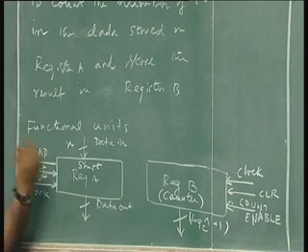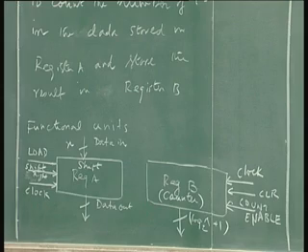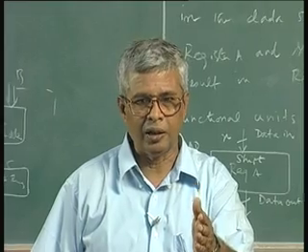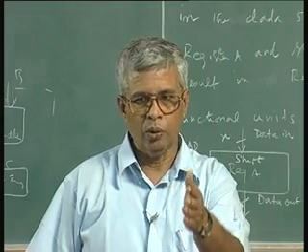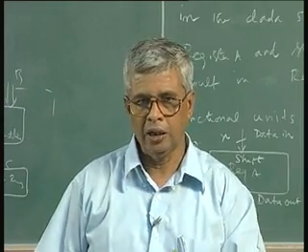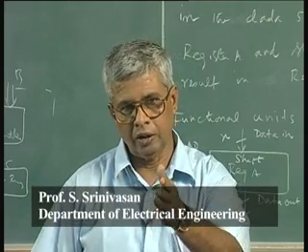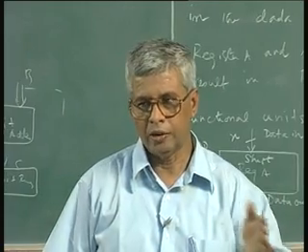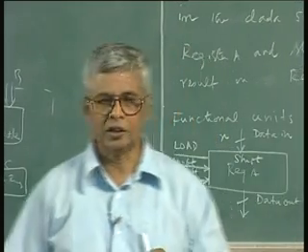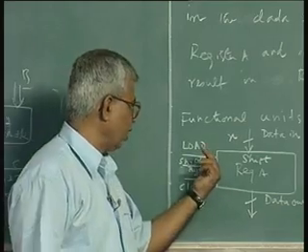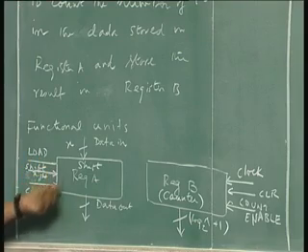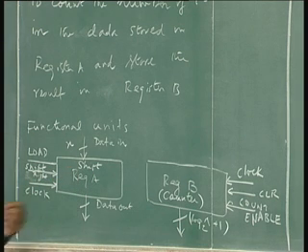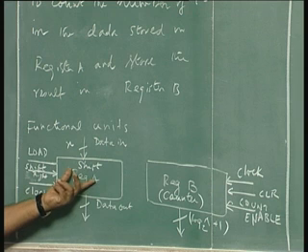The algorithm we are going to use, and there are several ways in which you can do this problem, is to look at the LSB, the least significant bit of the word, and see if it is a 1 or a 0. If 1, add 1 to the register B, otherwise shift it and look at the LSB, always by shifting, till you exhaust all the bits. So, we need a shift register with a shift right feature, a loading feature, a clock, data in and data out. These are the specifications or the requirements of the register A.